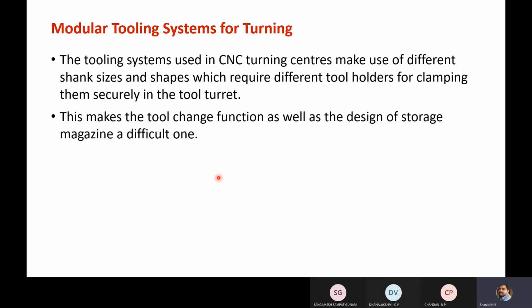Okay, you need not waste time regarding tool change like in conventional machines, since the tool turret consists of more than one tool. It can accommodate 12, 16 like that. That means you can perform operations continuously one after other by making use of 12 different tools. Okay, that is possible in case of CNC. That means the time taken to change the tool should be very minimum, so that you can perform the operations quickly and reduce non-machining time.